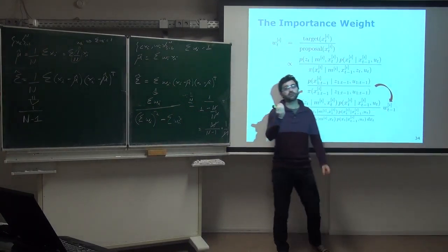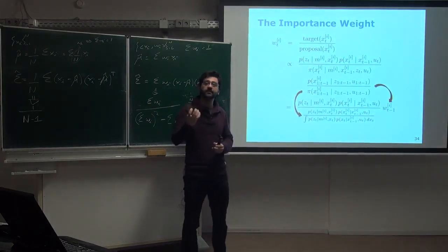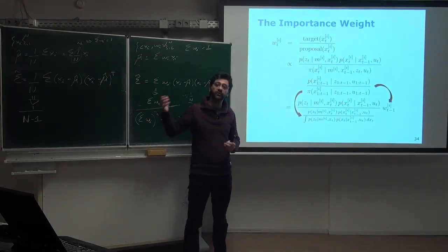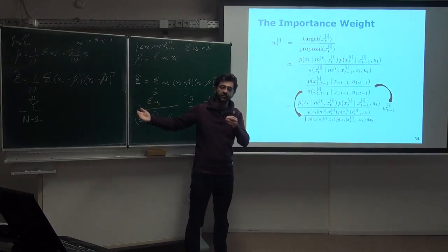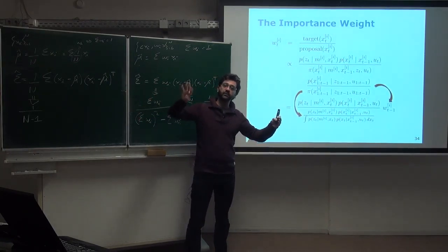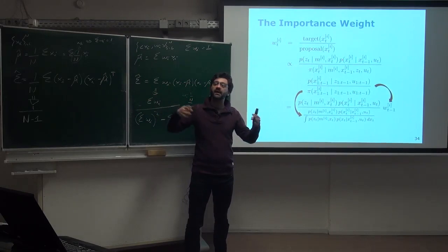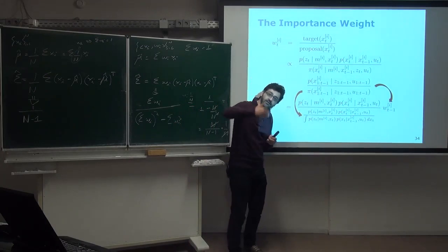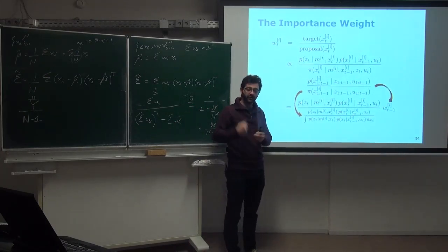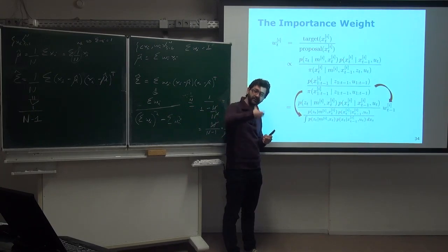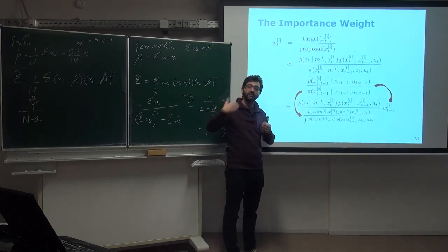If we didn't, the particles or the samples at the previous time step still keep the weight that they had before. So when we do an estimation on the full trajectory, we keep the weight until we do a resampling step. And the same thing holds if we do not normalize for the normal Monte Carlo localization. So basically, if a sample is propagated over time, you need to keep the weight and multiply the weights over and over time. Whenever you do a resampling, you basically reset the weight to 1 because you're sampling directly from the target distribution. So that's the idea of how these things work.